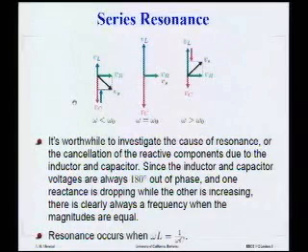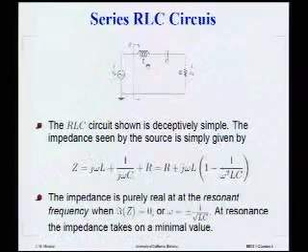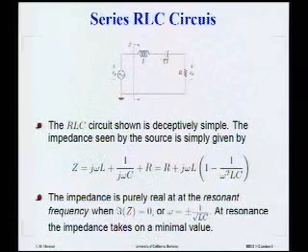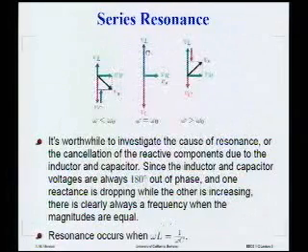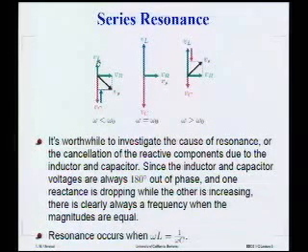Now below resonance means that, remember, at resonance this reactance is equal to this reactance, right? So below resonance, this reactance is actually larger than this reactance. In other words, because the same current is flowing in the entire circuit, the voltage across the capacitor is larger than the voltage across the inductor. Okay, it's a question. Oh wait, what is this diagram again?